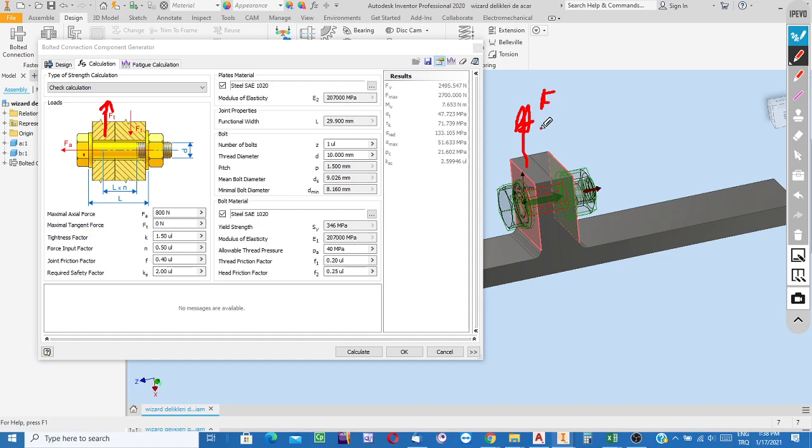Okay, and the other one will be under the action of such a force in the opposite direction. Say that we have such a load in addition to the axially directed forces, their effects just to shear the body of the bolt at this cross section, like the effect of a scissors. We have these forces. Okay.